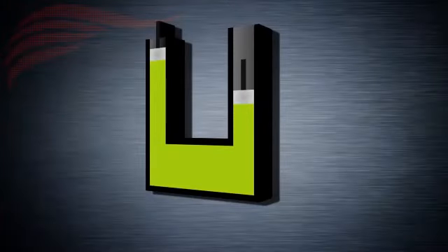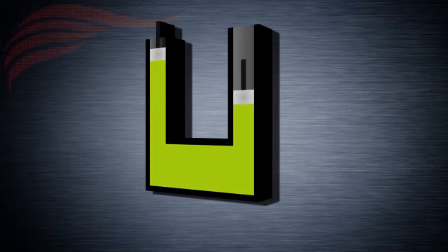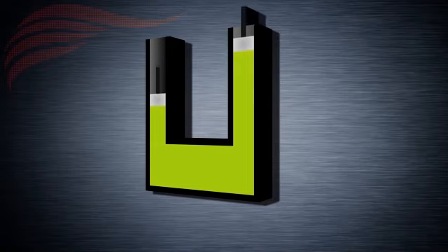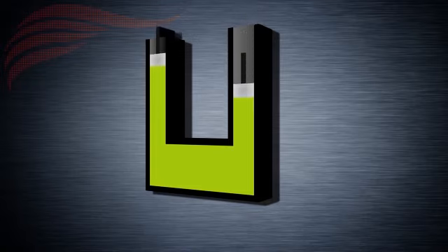To illustrate this, let's look at a container with two pistons of equal size. This is the simplest type of hydraulic system possible. If a force is exerted on the first piston, it will apply pressure on the fluid, which will be transmitted through to the second piston. Because the two pistons have the same surface area, the force exerted by the second piston will be exactly the same as the force that we applied to the first piston. This means that if we apply a 5 Newton force to the first piston, we'll get a 5 Newton force from the second. Let's take a look at what happens if we increase the size of the second piston.